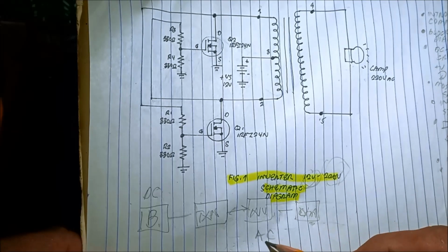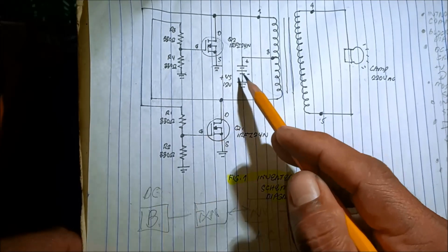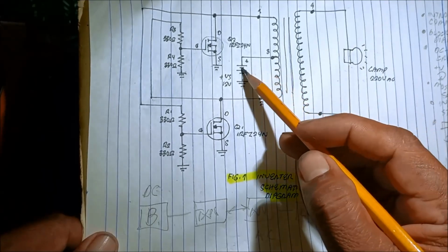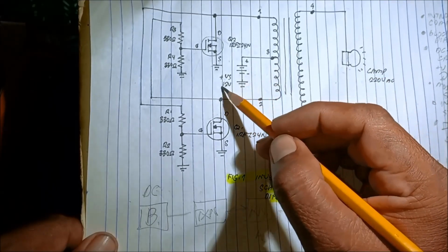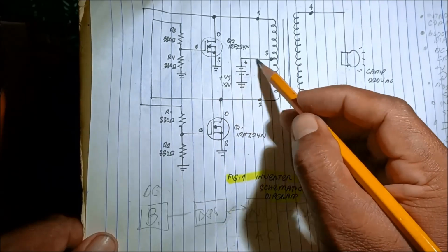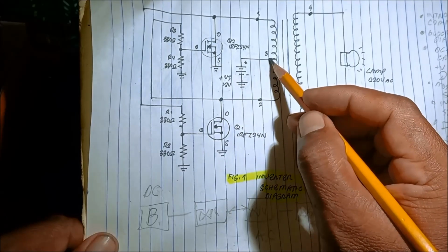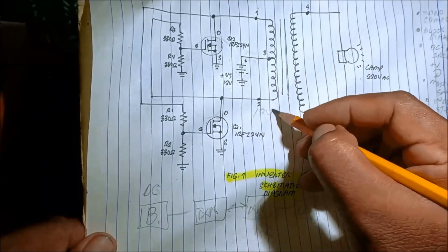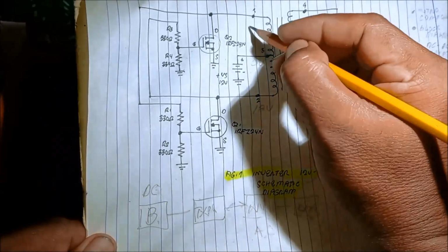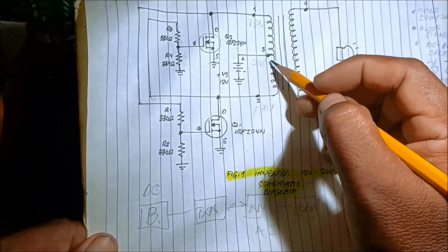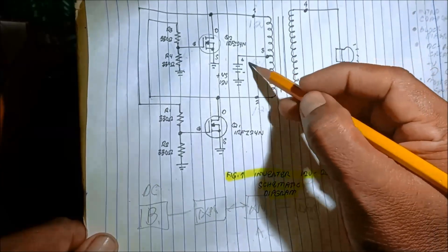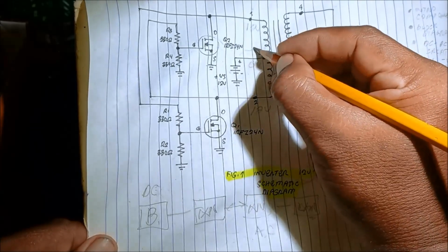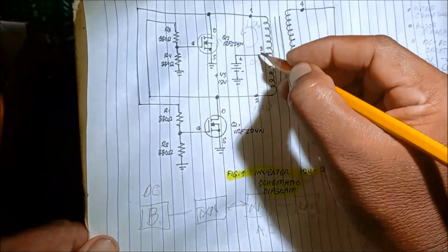How can we create the AC from DC, from battery? So we need to trace the current. When there is a battery here, 12 volts, current flows into the center tap. So there is a center tap of the transformer. This is 12 volts, 0 volts, 12 volts of the transformer. And then current flows into the center tap. It creates two current flows.